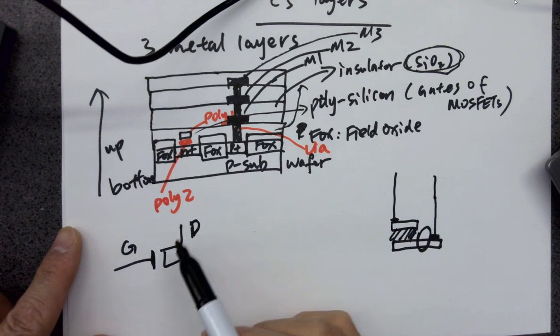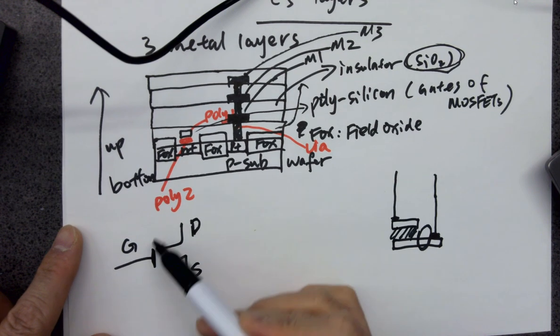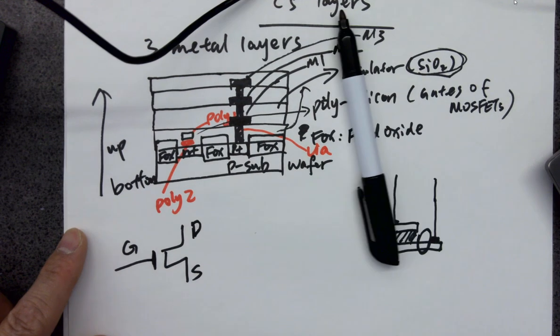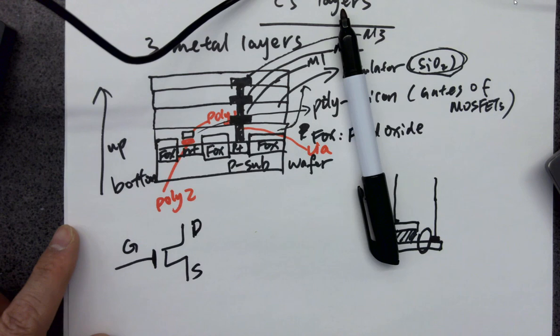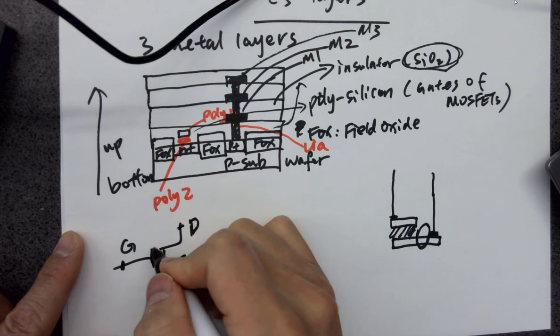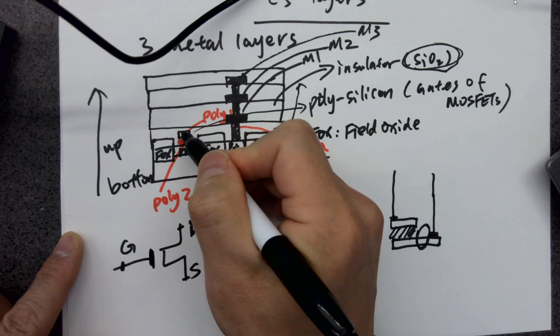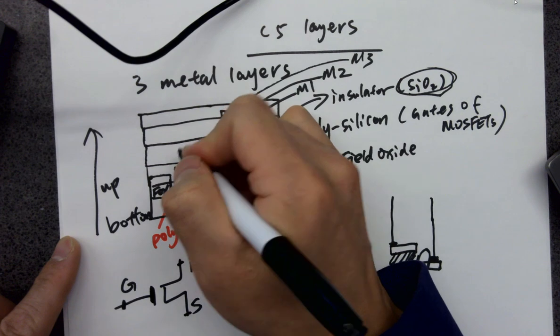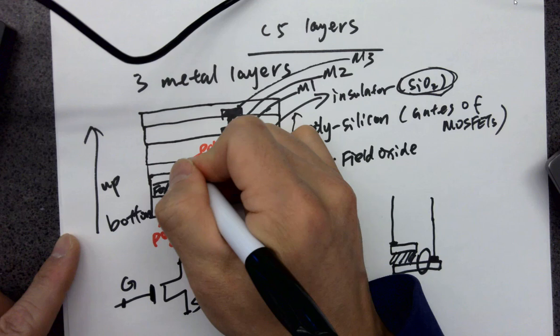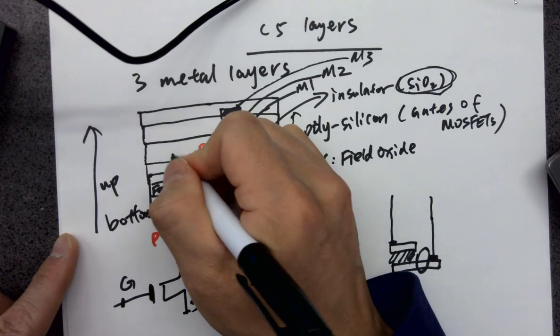Okay, so we'll talk about the details of this operation later. Don't worry about that. So this is just a transistor has 3 terminals, and the terminals need metal wires to either inject a signal into it or be probed by something. Okay, so these are metal. So this material over here for the gate is a polysilicon. It's not metal, but the thing is, we do need a metal to give a signal to it. So you need a via, okay, and you need a metal one.